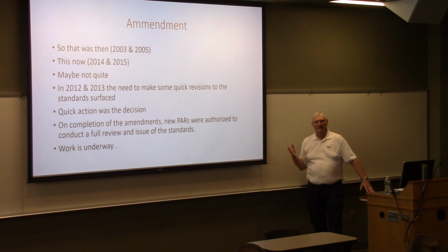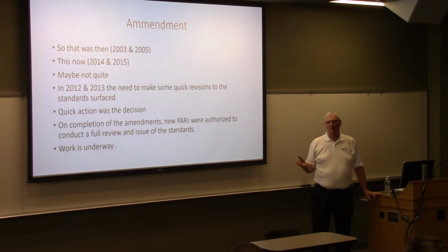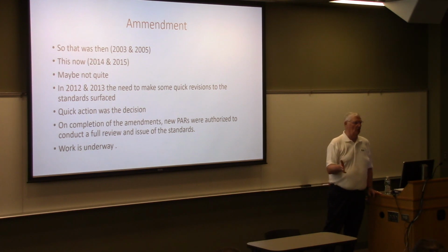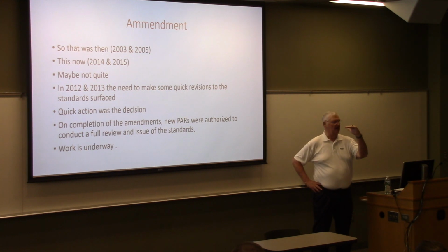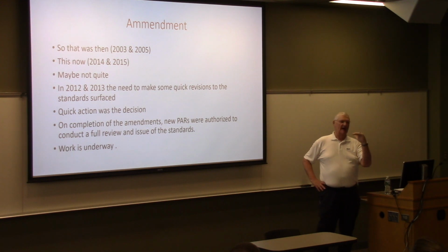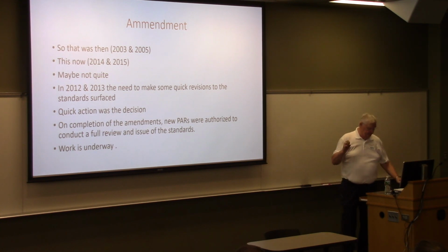So what the Federal Energy Regulatory Commission did was they said that we're going to change those requirements. Now you have to ride through low voltages. So if the voltage goes down to 60%, you've got to stay online and continue to provide power during that time so as not to worsen the event. If you go down to considerably below that, then you can get off the line. So these experiences caused us to have to amend the standard.